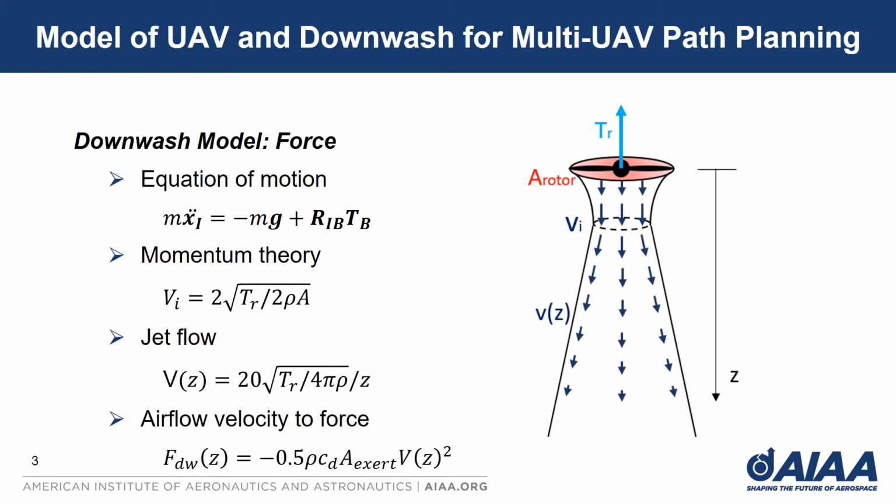So the third step is to obtain the airflow velocity that is a distance away from the rotor by using the jet flow concept. And the fourth step is to convert the airflow velocity to the downwash force, which is the force that the bottom UAV will suffer.